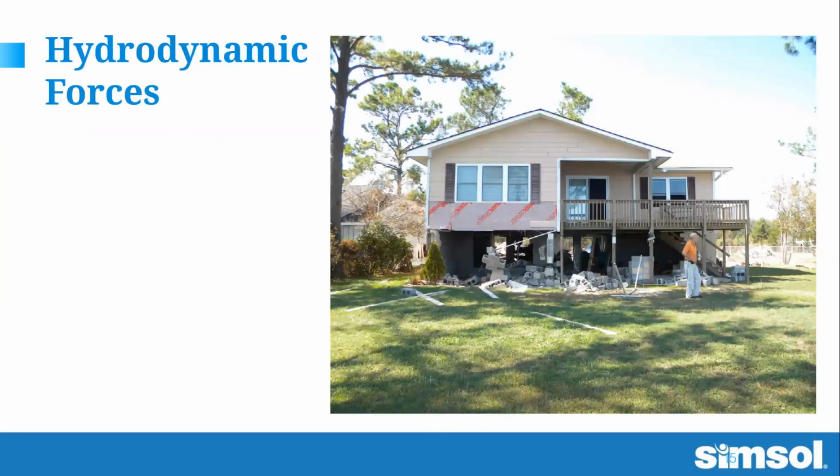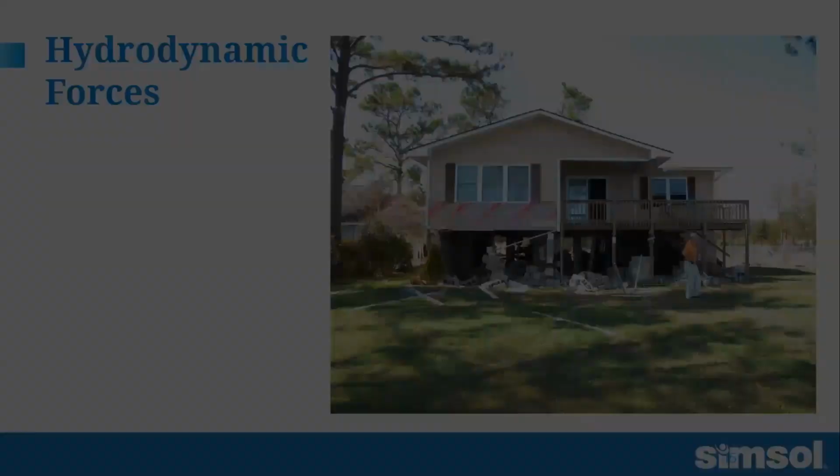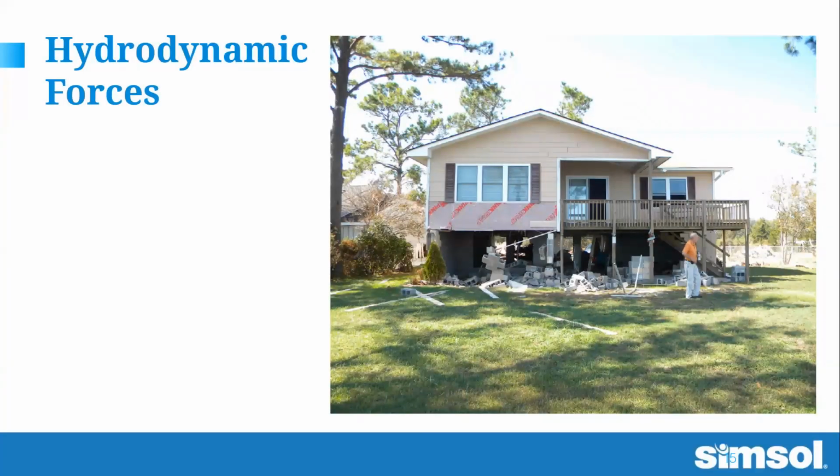Here's an example of a hydrodynamic force situation. The other thing with hydrodynamic force to look for is a direction of flow. Typically, the water is going to come from one direction and move through the building and out the other side. So all your damage is going to line up. If we look at the next picture, you can see here the previous picture. This was the backside of the house. The bay in North Carolina was directly behind me as I'm taking this photograph. So the water would have been moving toward the back of the house in this photo.